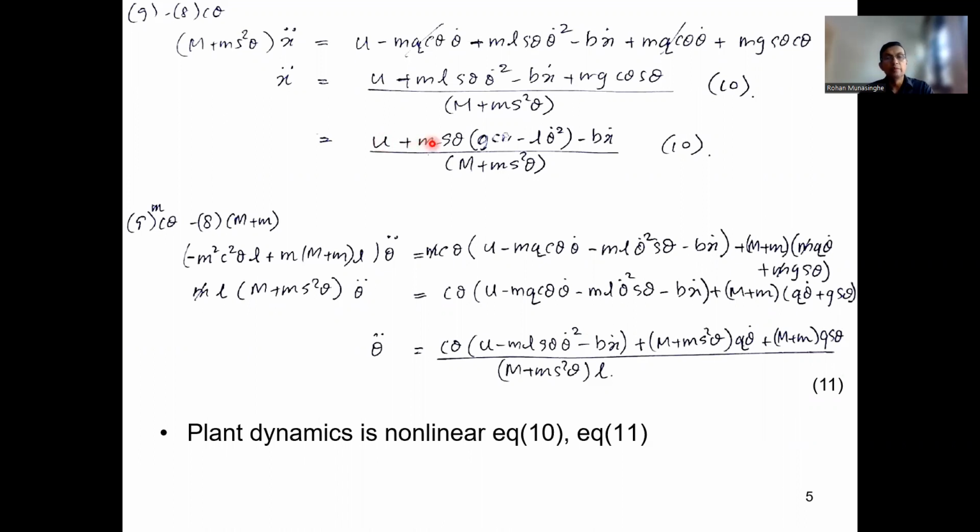And the mass of the pendulum, angle of the pendulum, length of the pole, and the mass of the cart, everything is there. The entire system is there, and based on their values at any moment of time, you get x double dot acceleration. And at the same time, if you look at the inverted pendulum pole, it has angular acceleration.